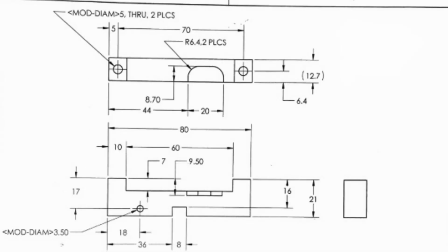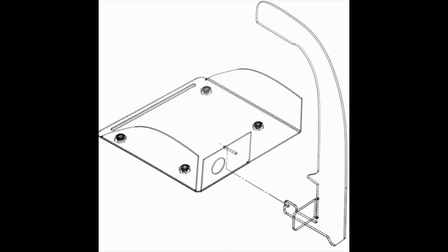This is an example of a Part 3-view orthographic drawing. This is one of the pieces of the maglev device, and it supports the PCB. The orthographic drawing consists of a front, right, and top view. It also contains dimensions that describe the full shape of the part, including characteristics of each dimension as to whether it's a diameter, a radius, or a linear dimension. The solid lines indicate part edges or tangents, and the narrower lines, such as the crosses through the circles, indicate center lines or holes.